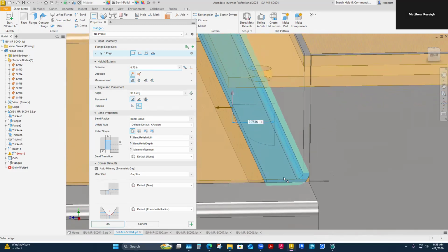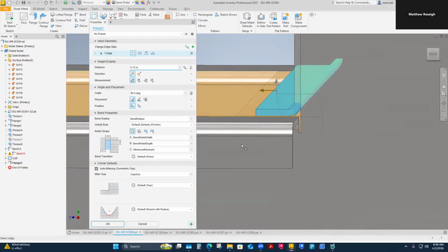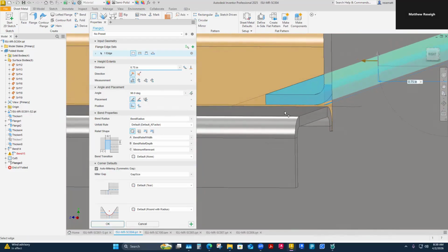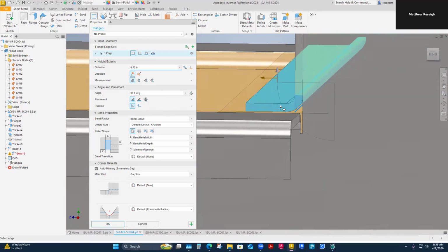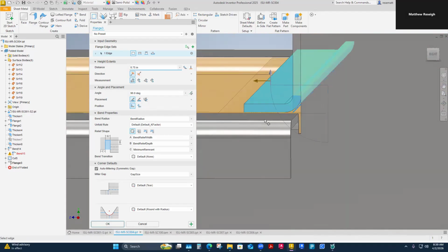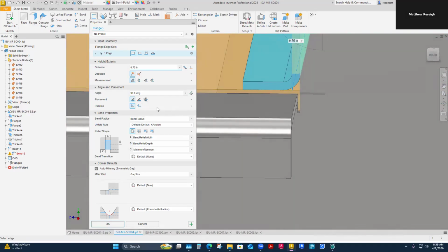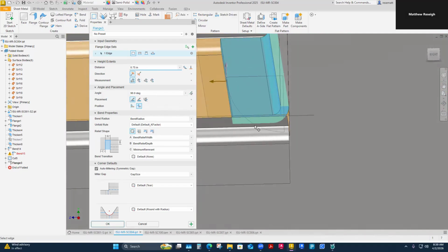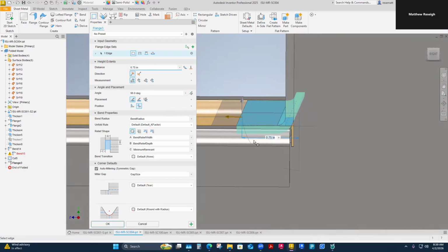So I'm going to stiffen that up by adding a 3/4 inch flange. And I think I just had to pick this instead of this direction. I want it to drop and be flush with my finished flanges here because my lid's going to span across there. And I don't want this to have an interference or higher than the top surface of this flange. So I think the only thing I had to do was, yeah, I picked 0.75 as my length and I chose to drive this down like that.